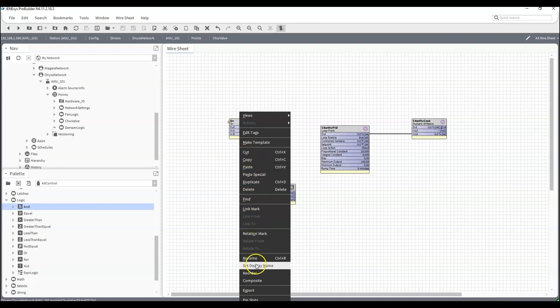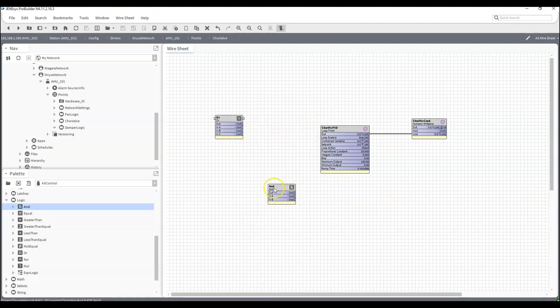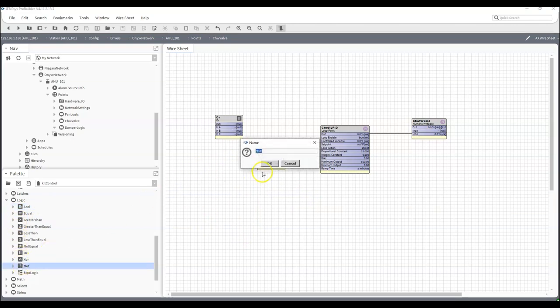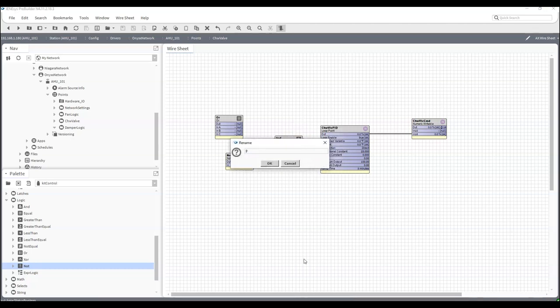So I'm going to use 3 here. So I'm going to pin out A, B, and C. I also need to make sure that we have fan status and then we're not in economizer. So I'm going to put a not here and just put not econ. And we're going to say this AND block is the valve and the PID enable.